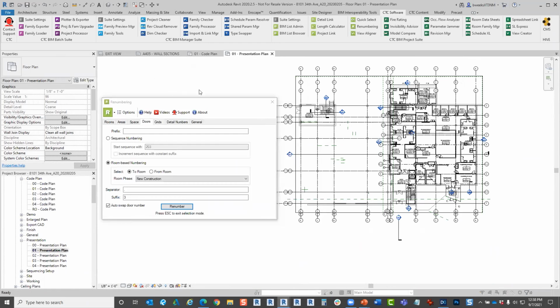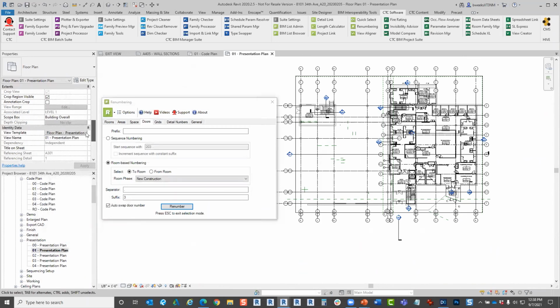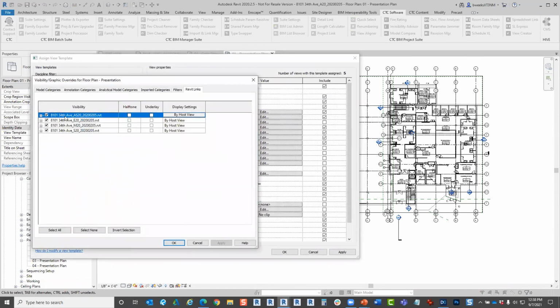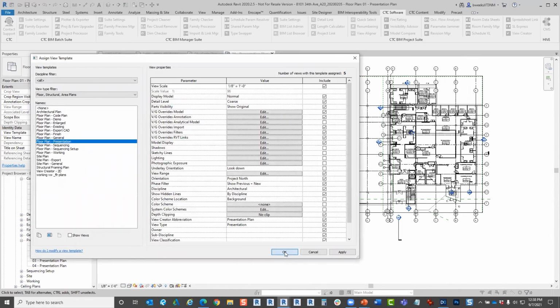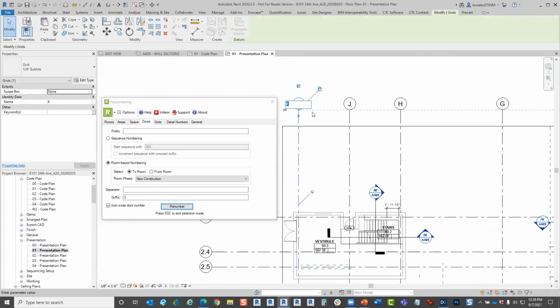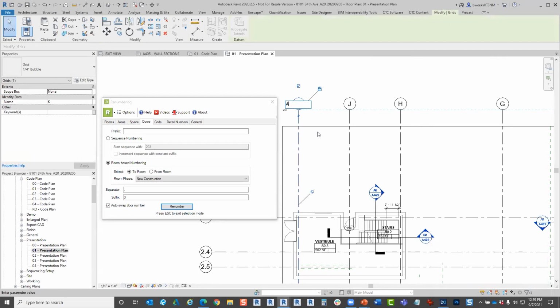And then let me do grids. I'm going to do grids real quick here because the grid renumbering is huge too. And when I show this off, I always get the oohs and ahs because grids have always been in Revit a huge pain point of having to renumber our grids because of the fact that we can't trick Revit into letting us do it. We can't have duplicate grid names. And so we have to almost double our work.